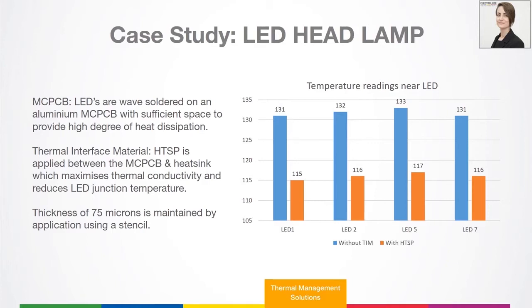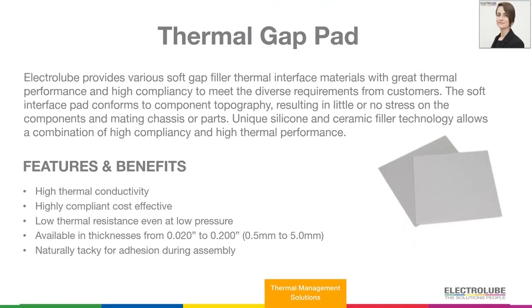application. So thermal gap pads, they're soft materials. They are very compliant, so when you feel them, you can squash them down, you can make them fit to the contours of the interface. But in order to achieve that, you do need to have some pressure there to make them squash down into all of the gaps. They don't impart any stress on components because they're so soft, and they're easy to apply. Simply cut to shape and put onto the device, place them on. So they're easy to rework as well. Thicknesses are quite a lot higher than a thermal grease, because you're starting roughly around 500 microns.